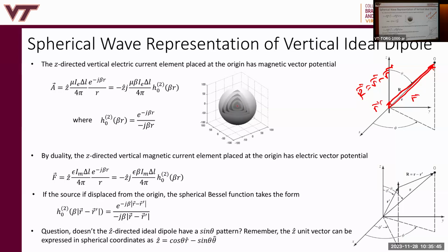Okay, so that's the coordinate system. Remember, when we had an infinite line source, we ended up with H02 when it was at the origin, right? The 0th order Hankel function of kind 2 with beta naught rho as the argument. So the 0th order of the Hankel functions, the cylindrical waves, represent a perfect cylinder expanding. You remember that?